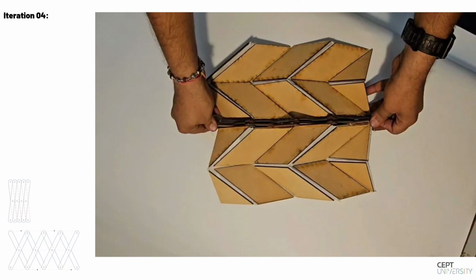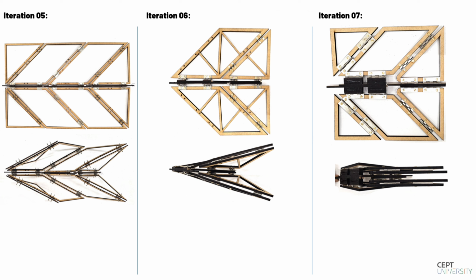To tackle that, I shifted from fabric and edge-based scissor solution to a direct hinging mechanism at the central mountain valley fold, simplifying the design by using metal hinges as primary connector between flat panels. Folding failed beyond the first panel as the second rhombus-shaped panel resisted folding. Upon analysis, I found that extended bolt heads act as an obstruction, preventing full articulation. This failure emphasized the importance of flush integration in deployment system, especially in tight folding geometries.